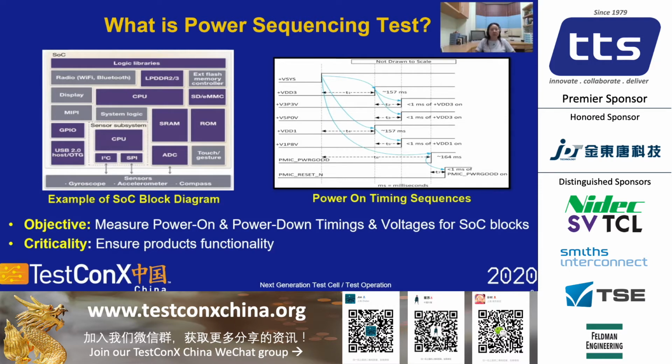In fact, for power sequencing tests, there are two different timings or voltages that we focus on. One is when we first turn on the system, where you measure the power up sequence, and then when you power down or terminate the SUT, we measure the power down timings and sequencing. All this is critical to ensure product functionality and also reliability.